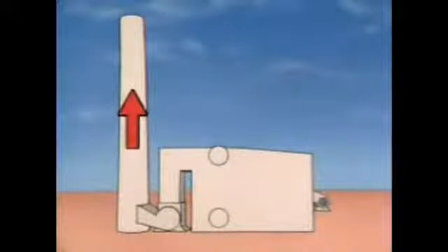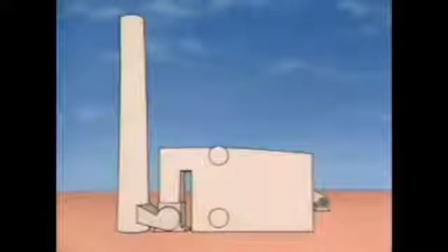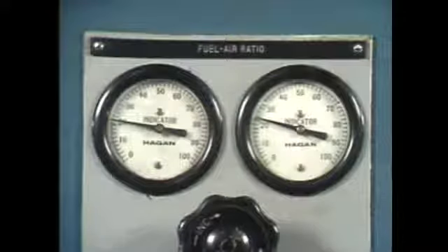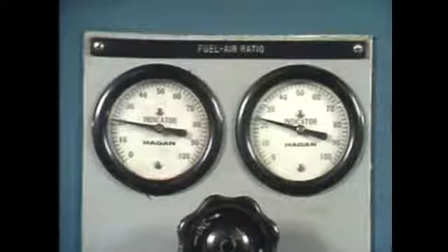On the other hand, if a boiler gets too much air, some of the fuel is used up to heat the extra air. This heat flows out of the boiler with the combustion gases. As a result, there's less heat available to produce steam. Most boiler operating procedures specify the proper fuel-to-air ratio. In addition, many boiler control systems automatically adjust the fuel and air mixture as boiler load changes.